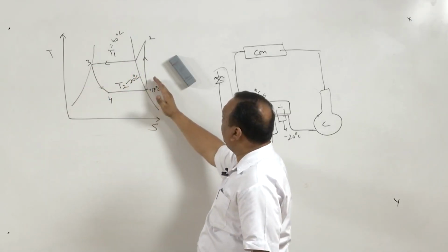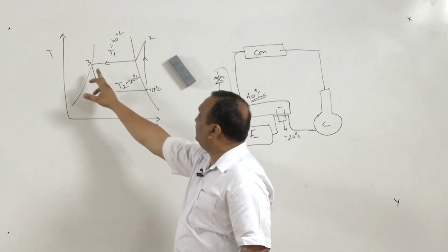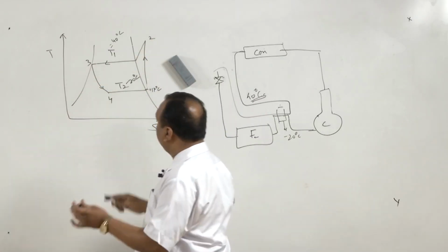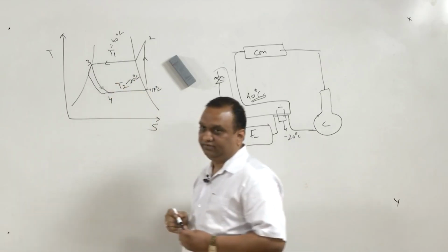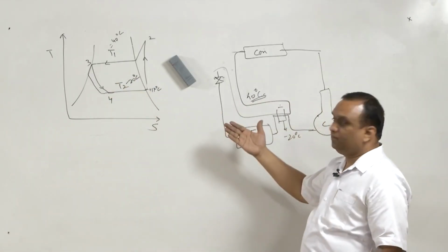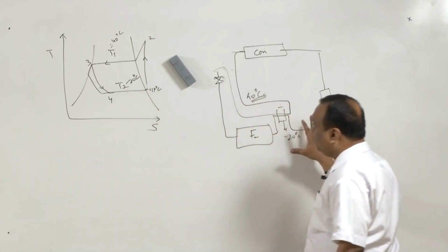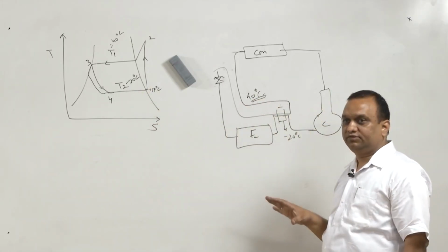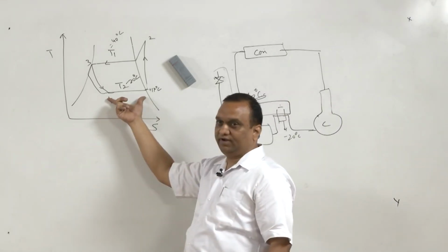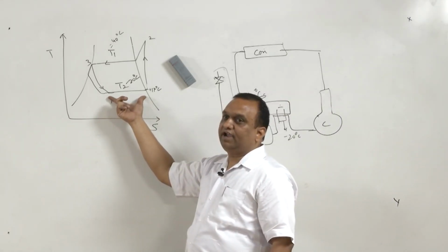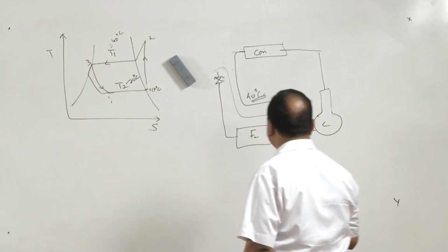When we are superheating the vapor, the compression work is increasing. At the same time, when we are subcooling the liquid, the refrigerating effect is also increasing. So, here also, through this arrangement, the COP may not increase for some of the refrigerants, but definitely we are getting more refrigerating effect with the same unit.